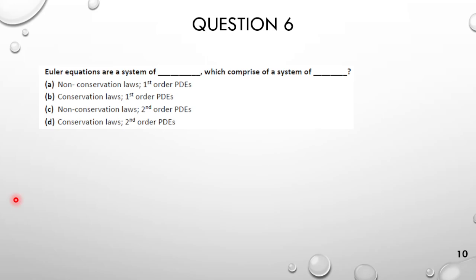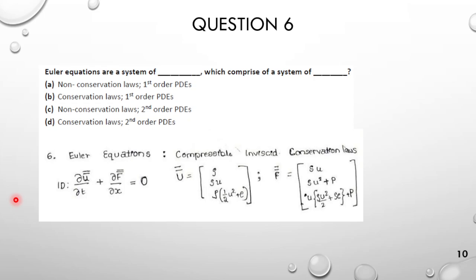What is the mass conservation which you have in the Euler equations? The first term is dou rho by dou t. Okay, so density is varying with respect to time here. Yeah, you can say it to be both because you can ignore the term, okay, of this particular dou rho by dou t, but it is mainly intended for compressible flows, not incompressible.